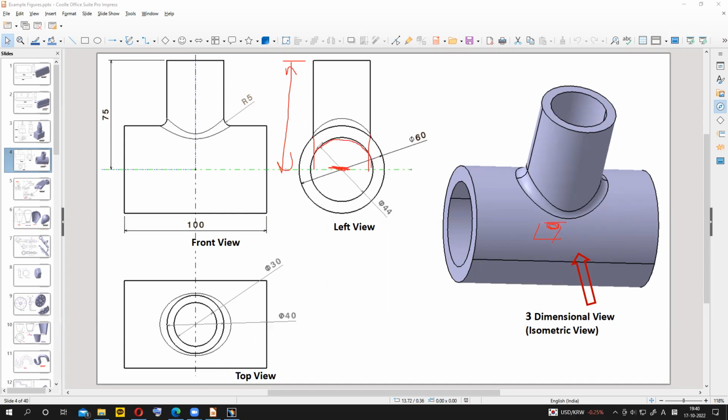Later we have to make a pocket. The other thing you can do is make a plane here and sketch there, but then we have to delete the extra projection inside using a pocket.